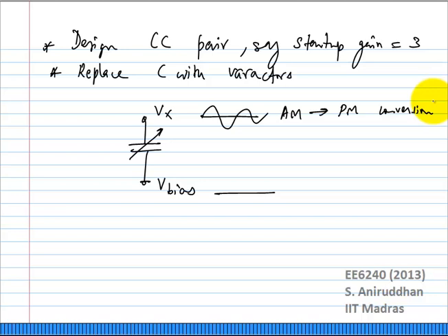Especially since this capacitance is relatively large, it is a major portion of the total fixed capacitance we have in the VCO. What happens is, the KVCO will be very large. Fundamentally, that's what we are saying. If all the fixed capacitance is just variable capacitance, you have a large KVCO, because the DC tuning voltage is fixed. You can go from 0 to VDD, right? The actual tuning range may be several hundred megahertz.